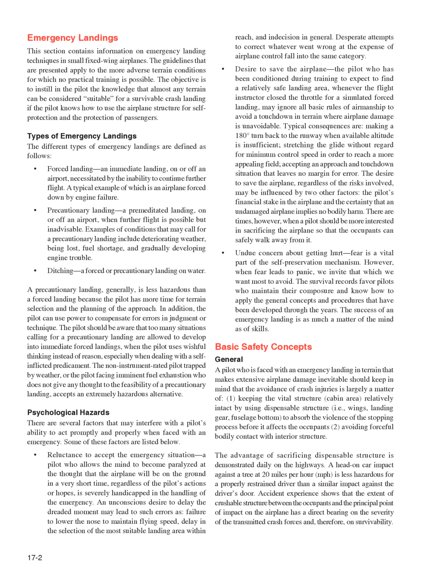emergency. An unconscious desire to delay the dreaded moment may lead to such errors as failure to lower the nose to maintain flying speed, delay in the selection of the most suitable landing area within reach, and indecision in general. Desperate attempts to correct whatever went wrong at the expense of airplane control fall into the same category.